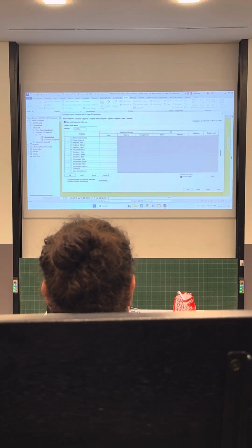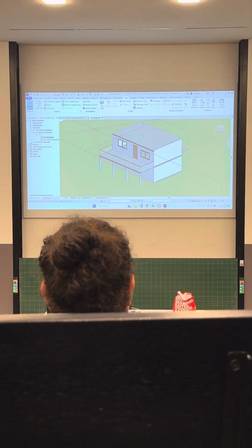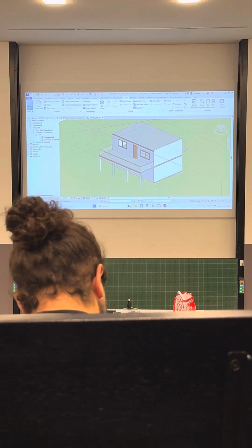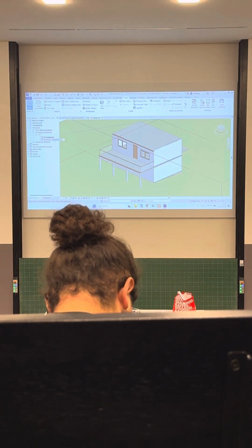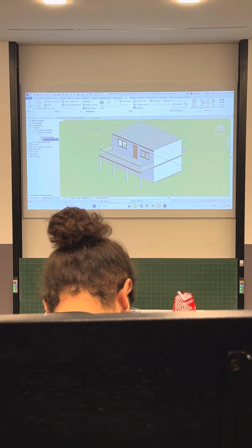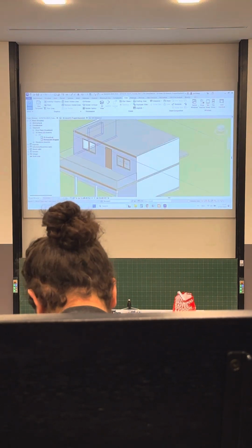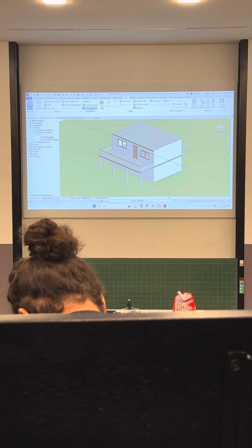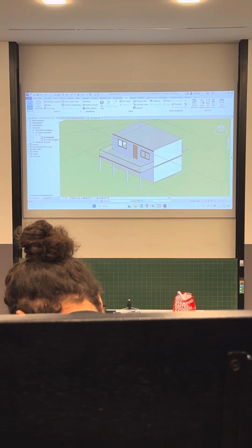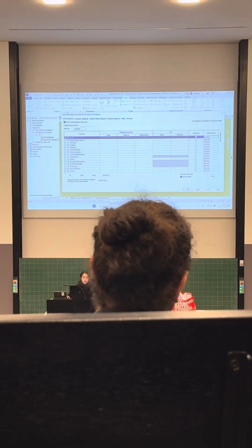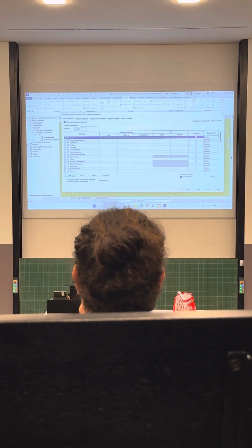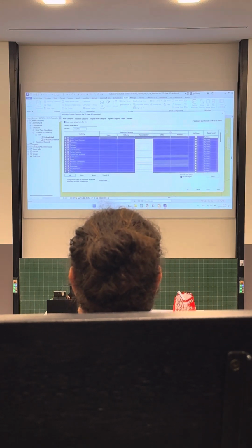We duplicate the view first, and we choose the analytical 3D view, which we want to use for structural analysis. We go in here, because we want to preserve our original view, but we created this one just for us. And we go into the View tab, into the Graphics section, and the Visibility and Graphics button here. And we can click here All, and just untick it.